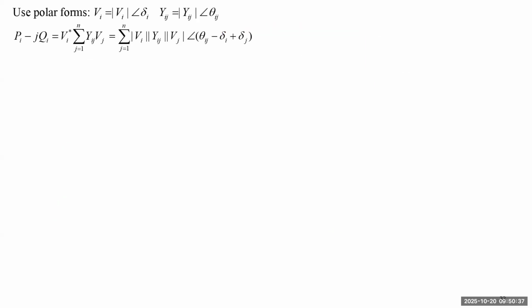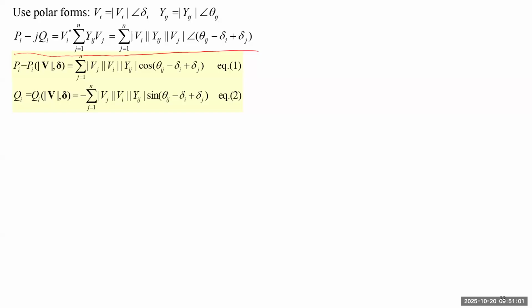All right, so now let's look into the more detailed steps to form the Jacobian matrix for iteration. We use polar form. This is our power flow equation, and we want to write two equations. The first one represents the real part, the second represents the imaginary part. The first equation will tell P as a nonlinear function of, so here you see everything becomes an absolute value.